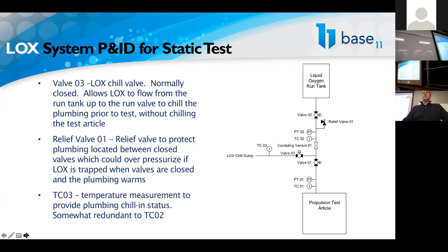But if we slam the valve shut, there would be a water hammer there, right? There will be, but again, if your propellant lines are sized to have a reasonably low velocity, you're managing the momentum, right? Because it's mv squared. So as long as you've sized your propellant lines appropriately for the velocity, closing the valve should not create a significant water hammer.